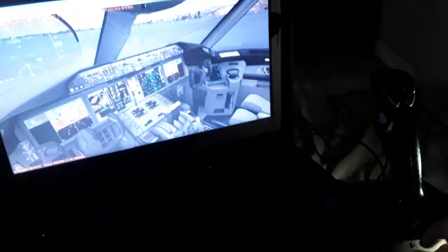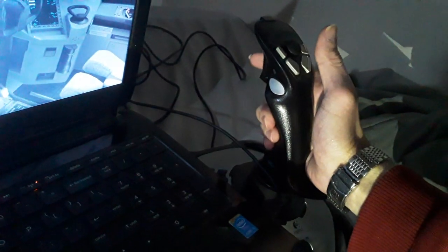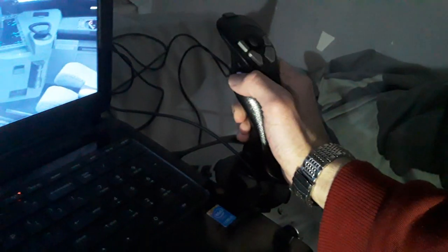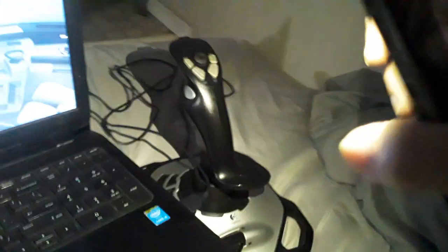In the Airbus we have also other systems, so you can use an override force for the Boeing aircraft. You move the slider back and forth, and you see the engines increase and decrease like this over here. So this is the main flight controls. You have in the Airbus the side stick priority button. You can take priority to the left and the right side, push to talk, and disengage the autopilot over here. So this push to talk disengages the autopilot in the Airbus aircraft.